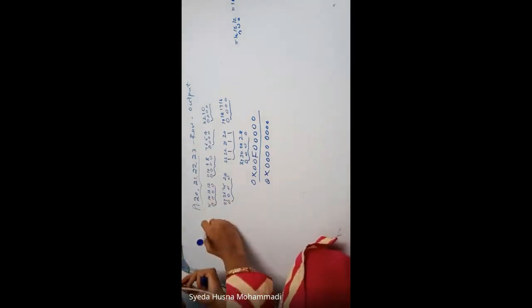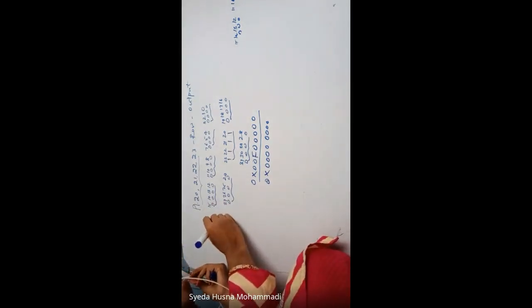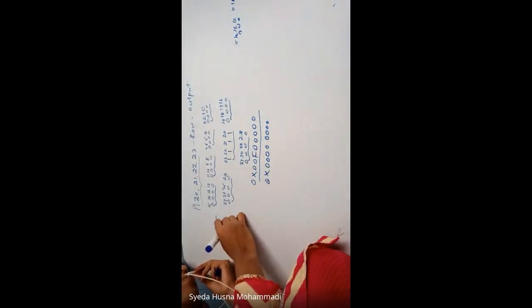So if no column is being pressed, the columns are connected to port 0 pin number 15, port 0 pin number 16, port 0 pin number 17 and port 0 pin number 18. So this is where the columns were being connected to. If no key is being pressed, the values on these pins will become 1 1 1 1: 15, 16, 17, 18.